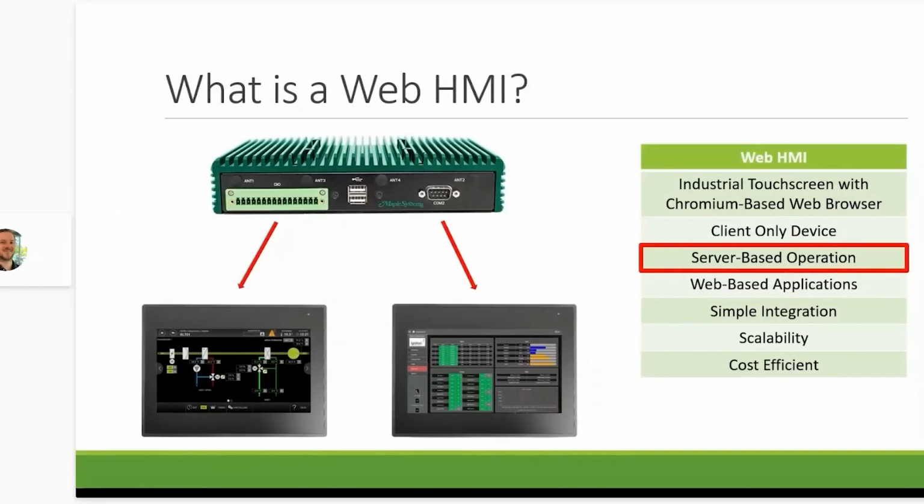Since the Web HMIs are server-based systems, the central server does all of the actual work, whereas the Web HMI simply acts as the proxy for the control of operations and data, meaning nothing is actually stored on the Web HMI itself. In addition, URLs are stored directly onto the Web HMI, so users do not have to continuously input them. This setup is fantastic for better efficiency, reducing power consumption, and centralizing processing.